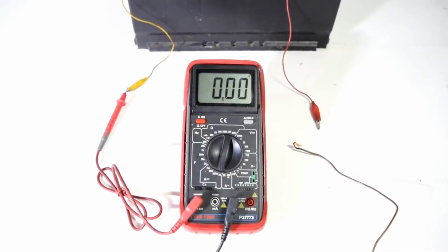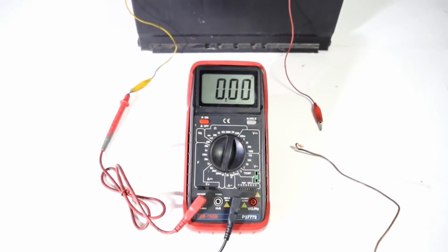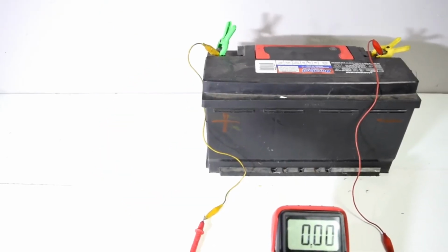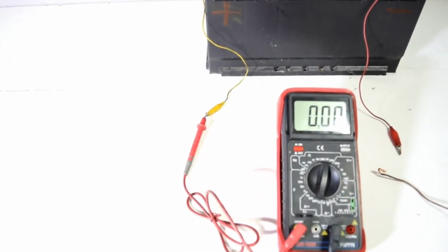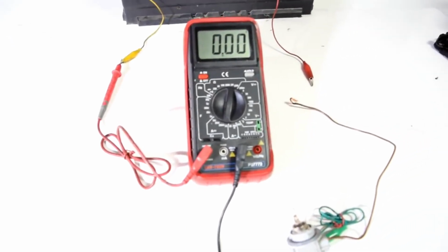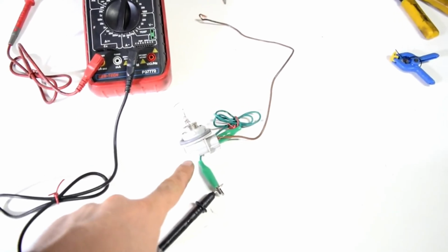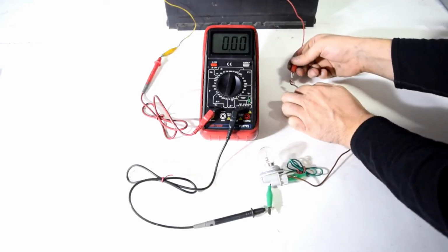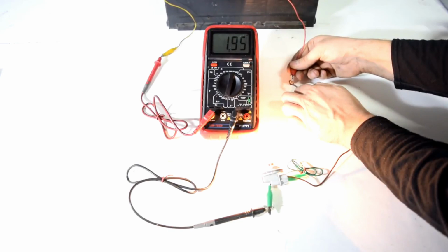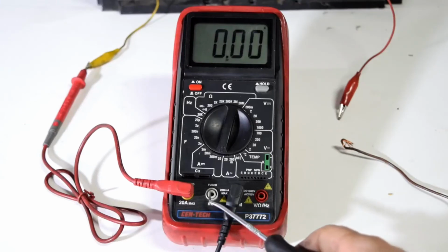And the way you measure amps is basically you place your multimeter on the power side of the circuit you're measuring. So here's the wire from the positive side of this battery. You place your red test lead closer to the power source, and then from there power travels through your multimeter, through the black test lead to the positive side of your device. And next, when we complete the circuit by connecting our ground side, our light bulb turns on and we get our reading, and as you can see we got 1.95 amps. So it was a great move putting our red test lead on this higher setting to measure 20 amps, otherwise we would have blown a fuse here.